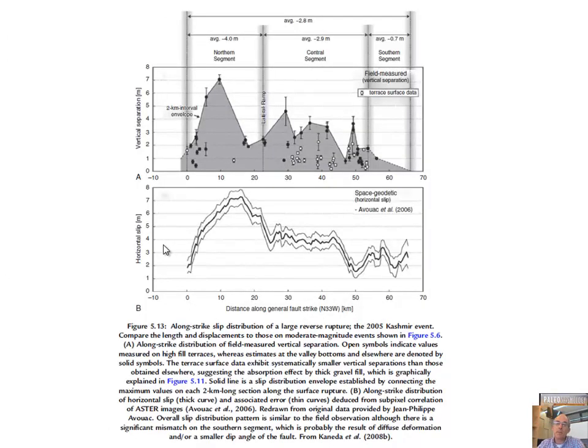This was some evidence from the Kashmir earthquake, and just because for the other kinds of faults, I had showed these same slip curves. So this is distance versus vertical separation, so some kind of vertical offset. And what you can see, and what their point was, is that it's 60 kilometers long, but has as much as 7 meters of offset. So it's a little bit high slip length ratio. Because if you think like Denali, remember Denali was 330 and it had peak slip of 7. So this is 5 times shorter, but still has large slip. So maybe distinctive for some reverse faulting events is they have high slip. And so it's thought that sometimes this means that the stress drop is higher. So the earthquake had more energy stored up, and when it released it, it put that much more slip out.